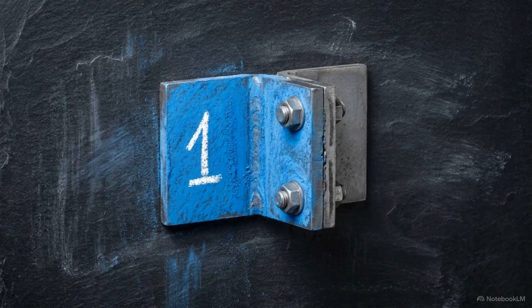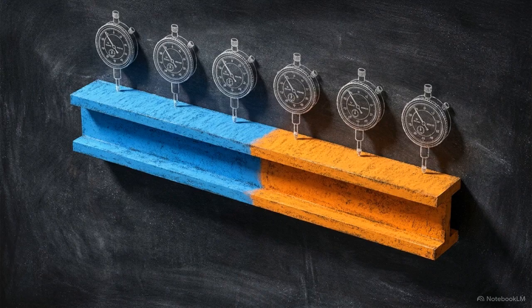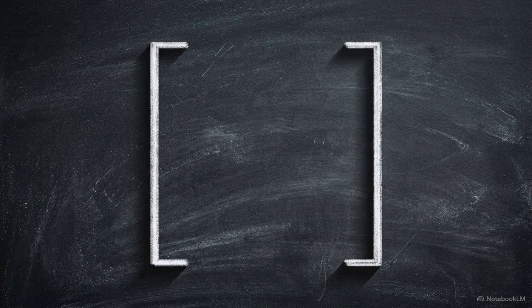We then define the element boundaries. Element 1 exclusively connects node 1 and node 2. Element 2 exclusively connects node 2 and node 3. With 3 physical nodes each possessing 2 degrees of freedom, the final global mathematical model must account for a total of 6 interrelated variables.